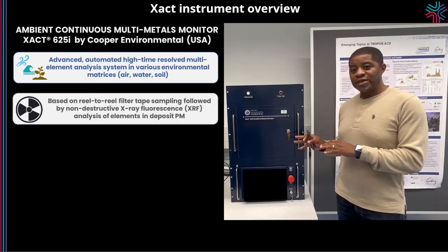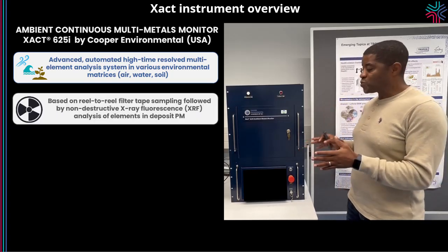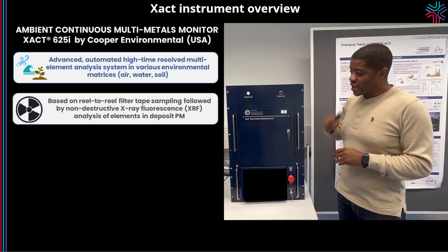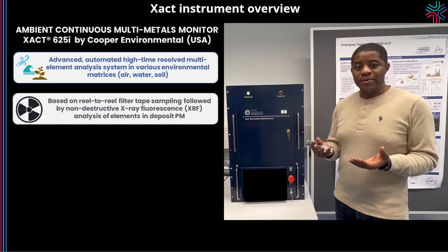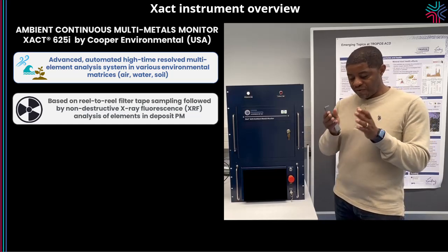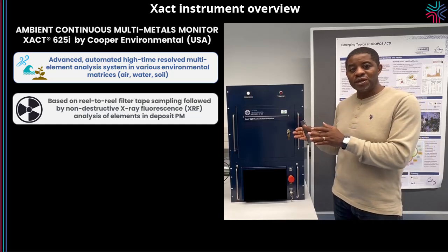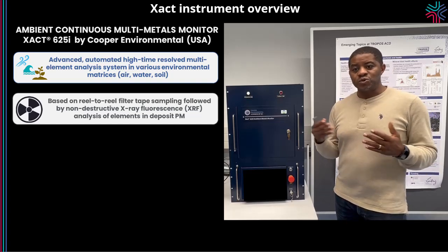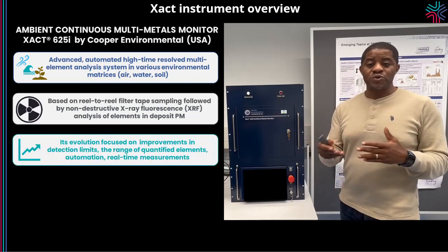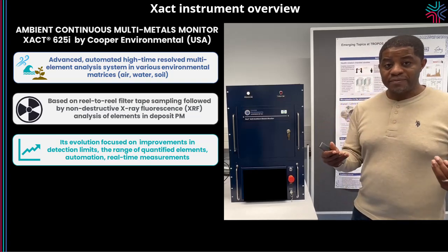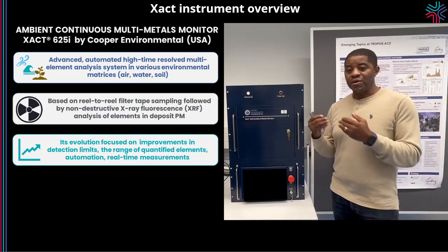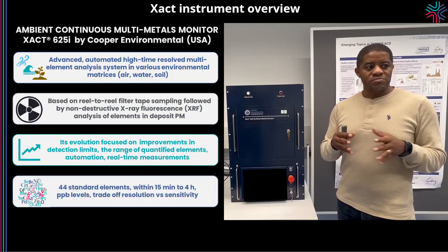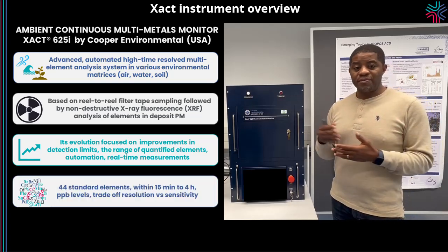The most important thing is that it's based on a reel-to-reel filter tape sampling system. Particulate matter comes in and is sampled on a tape, and the tape moves from the sampling system to a detection system, where we use the X-ray fluorescence technique to quantify these elements. It is non-destructive, because you can still analyze the filters after they have already been measured. One of the most important things is that the XACT has a standard protocol for 44 elements that you can quantify.